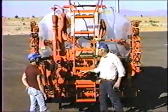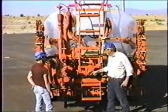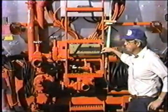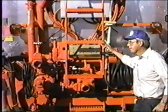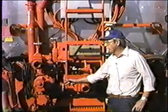Okay, the pump's running in forward. We just closed off the asphalt supply. We open this, now it's going to pull air in here. It's pulling air in the bottom of the pump. That old gear pump will pump air just about as good as it does asphalt. We've got the pump running at 200 gallons a minute, pulling air in here. Open this wide open so that it pumps a lot of air.